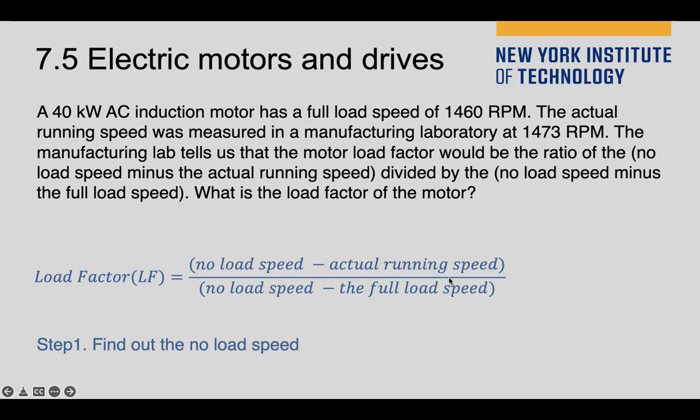So if we know one more parameter, that is the no load speed, then we can get the load factor. As you try to remember about the first question we discussed maybe 20 minutes before, if we have the full load speed, then we can obtain the no load speed.